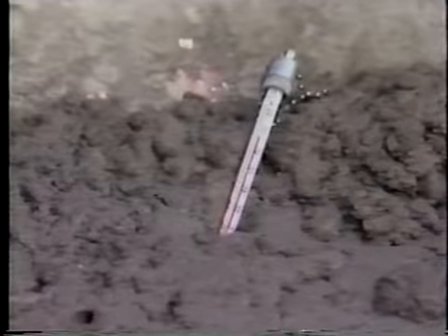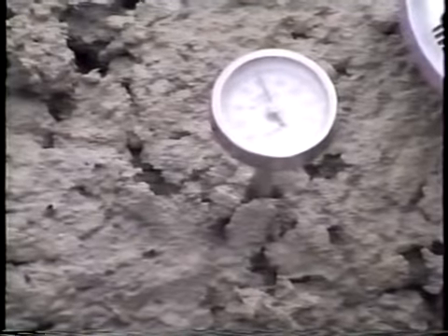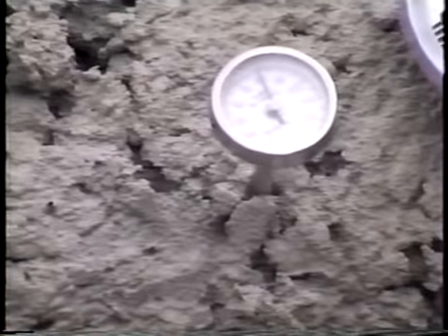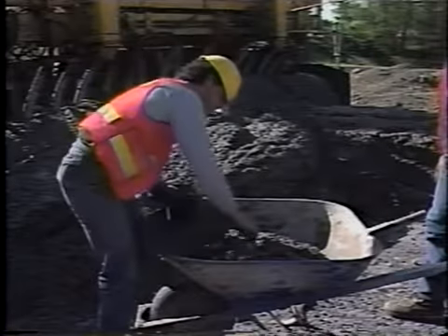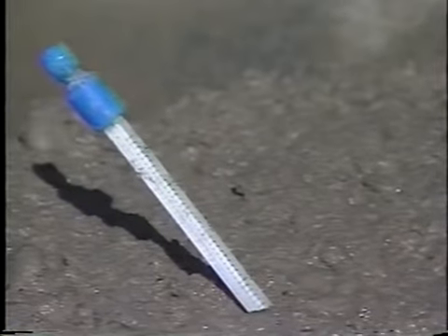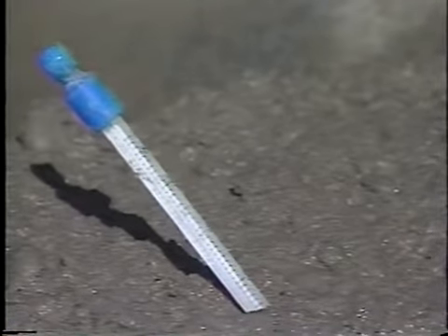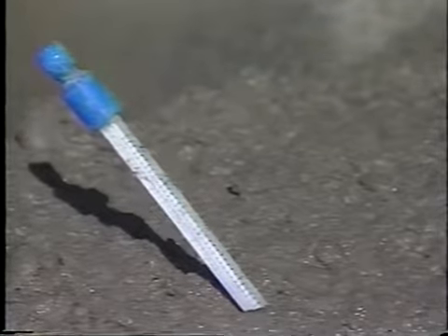All that's needed is a standard thermometer, such as an ASTM liquid in glass type, or a metal immersion type. The thermometer is inserted into the fresh sample so that the temperature sensing portion is submerged at least 3 inches.